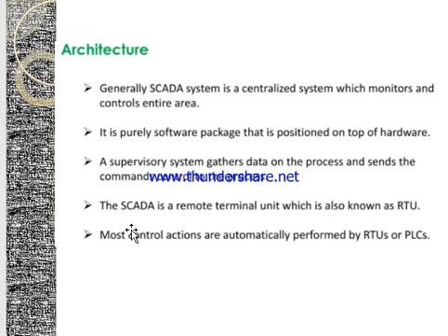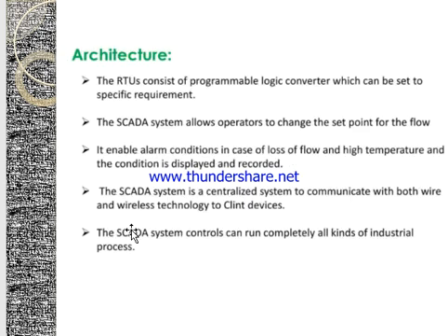While considering this architecture, generally the SCADA system is a centralized system. It will monitor and control the entire area. It is purely a software package that is positioned on top of hardware. A supervisory system will gather the data on the process and send commands to control the process. It uses a remote terminal unit and most control actions are automatically performed by it. So this consists of a programmable logic controller, which can be set to specific requirements.